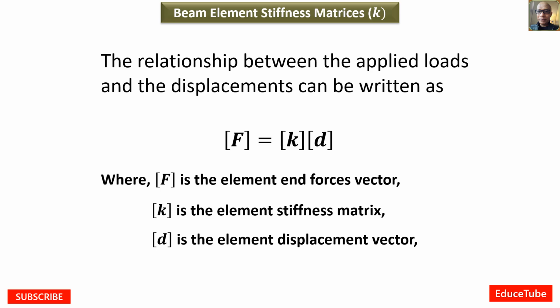And here I will develop the element stiffness matrix related to an element local coordinate system. In addition, I want to mention that I am not going to do the structural stiffness matrix, so I will not discuss anything about global coordinate systems. My discussion will be limited to the local coordinate system. Let's move ahead.